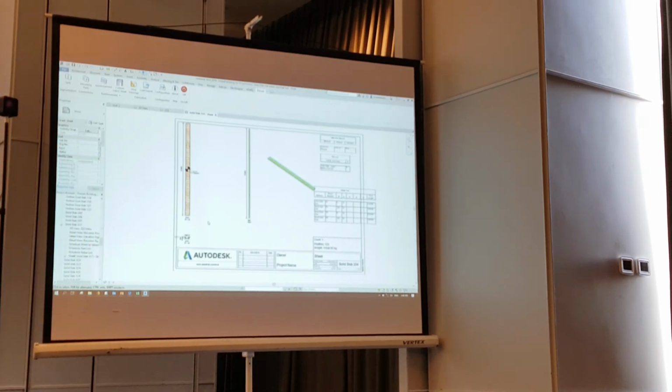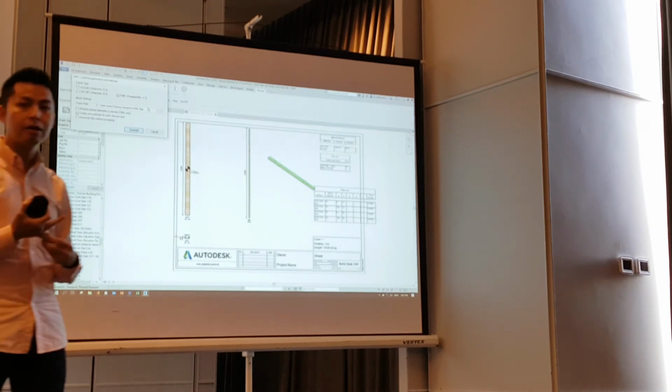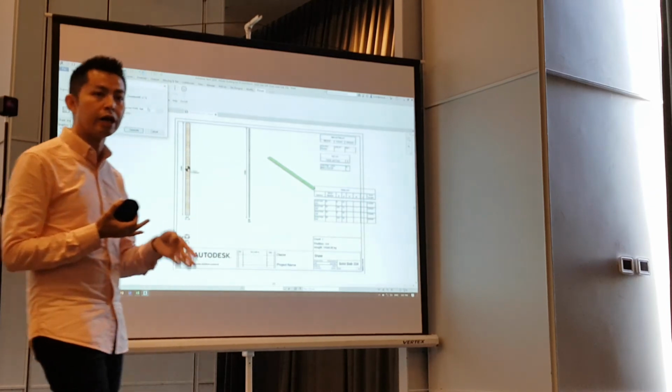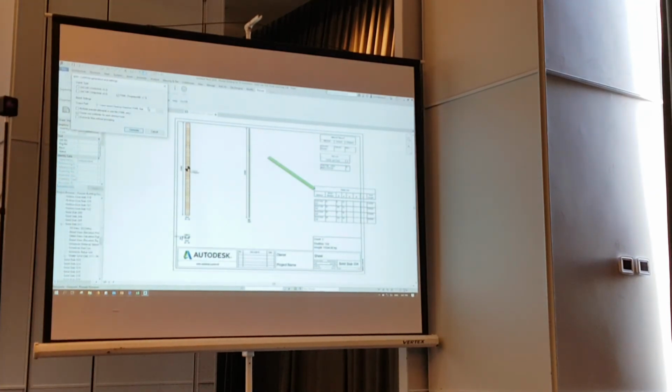No? Alright. Now, the other thing that is quite important to show to your client as well is the CAM export. If you click on the CAM export, it will export this particular item into a Unitechnic format or the PXML format. These two formats will be sent to the machines to do the automation or the machinery things and so on.